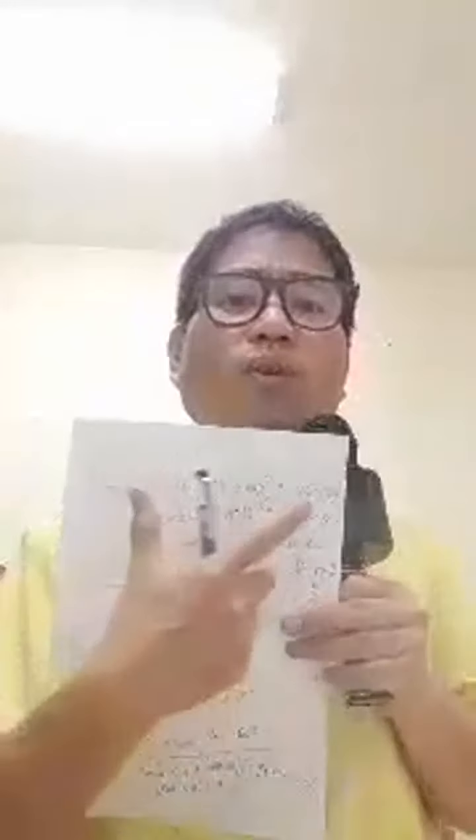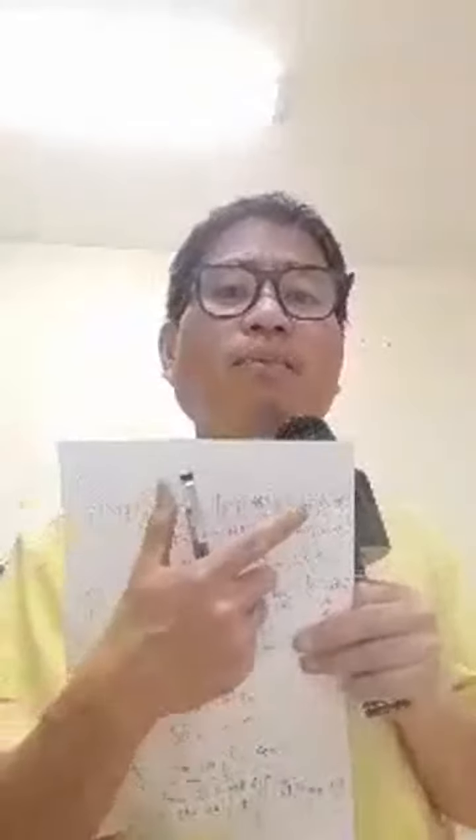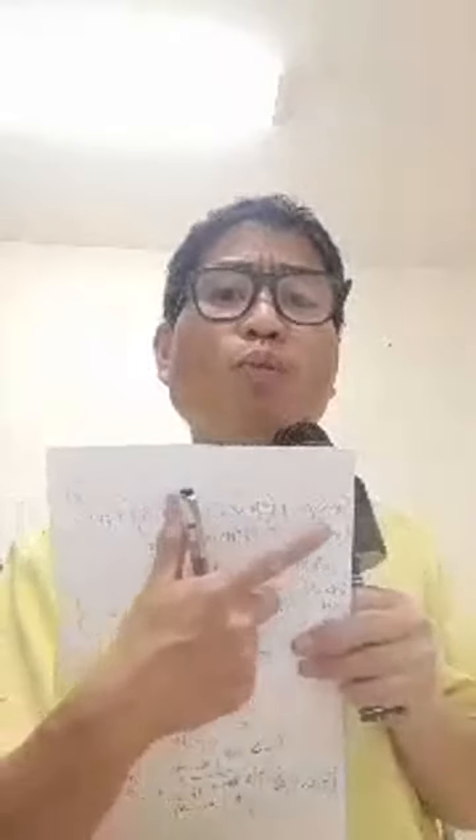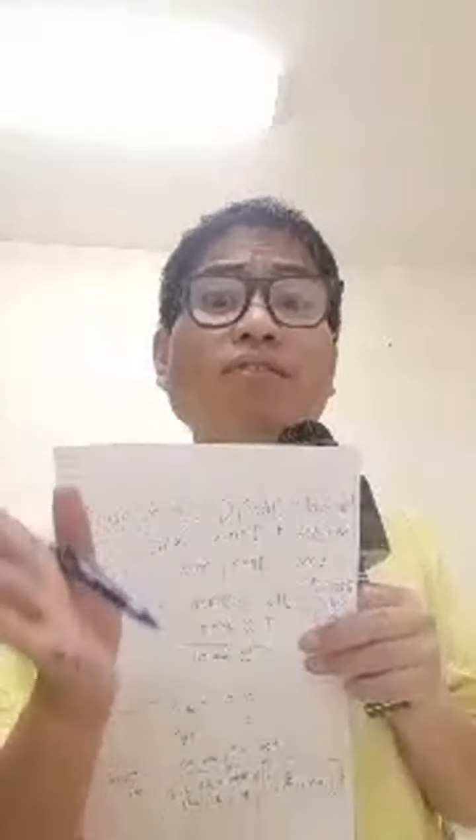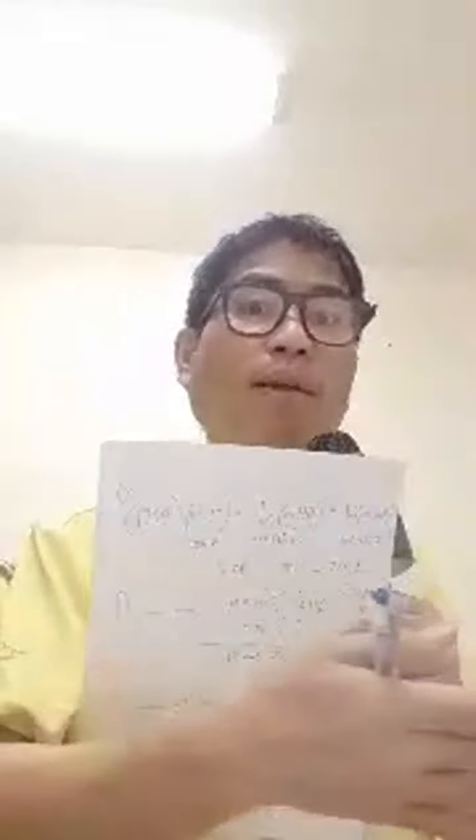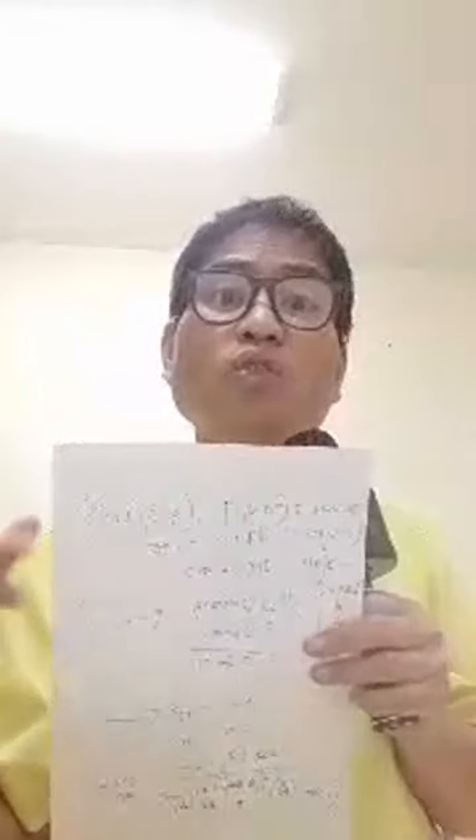So we need to go back again and you can solve for the mass fraction. I will leave that to you, guys, I am very tired. Anyway, the mass fraction here is very easy to compute already. You have the distillate, you have the bottom product, we have the feed. Now compute for the XW, accounting for the conditions in the problem. Then bingo, you can solve it.